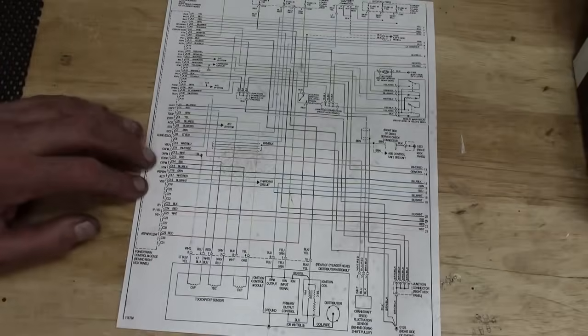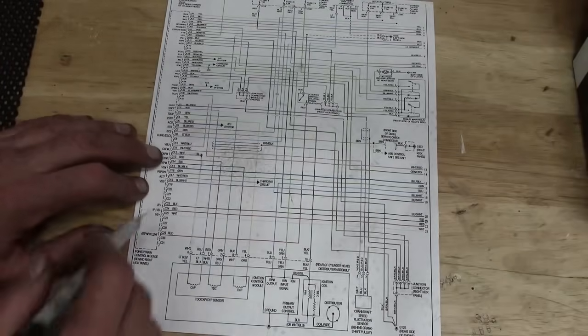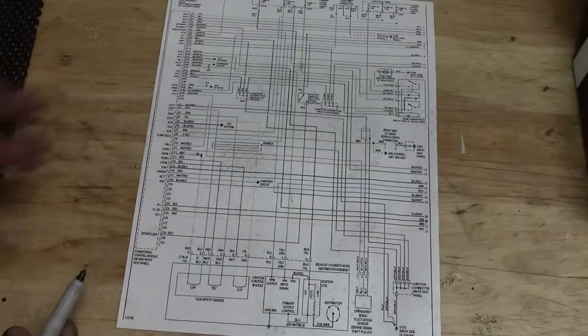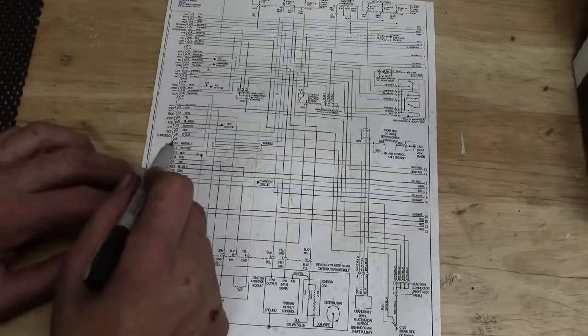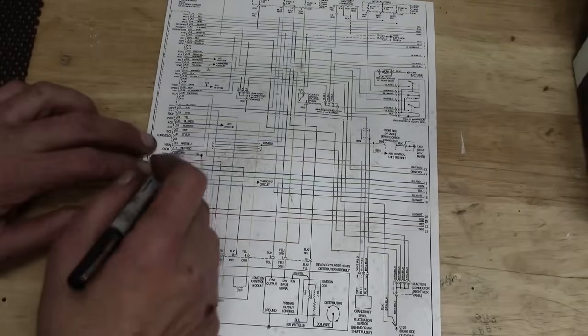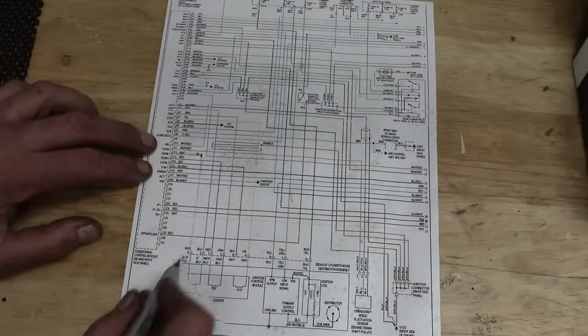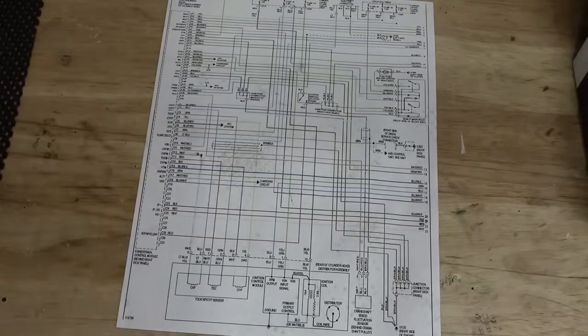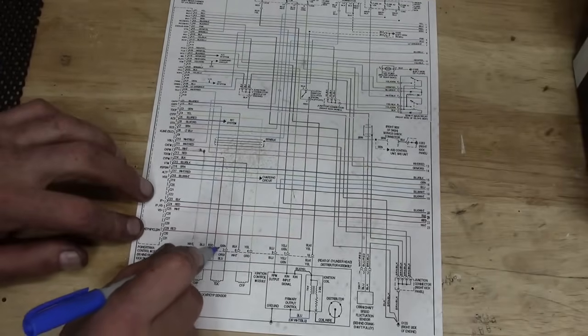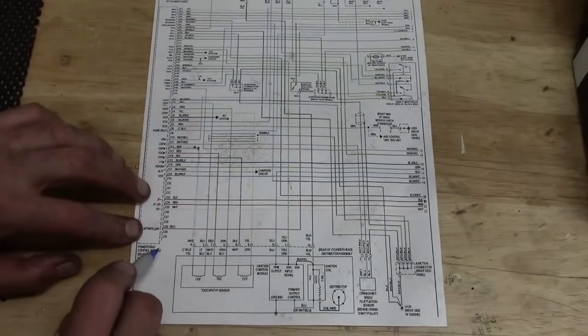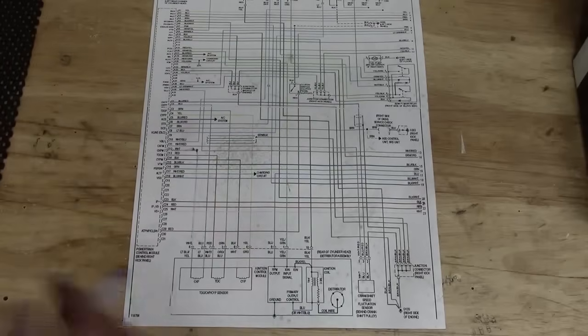And I am not sure what the M means. This is obviously going to be an inductive sensor. We know that from our training videos on cam and crank sensors, so I'm guessing maybe whatever the M is, it's either positive or negative. Maybe the other wire will be a clue. The other wire is blue, and you can see that they change colors after the connector. This is really common that you see that they change colors after the connector.